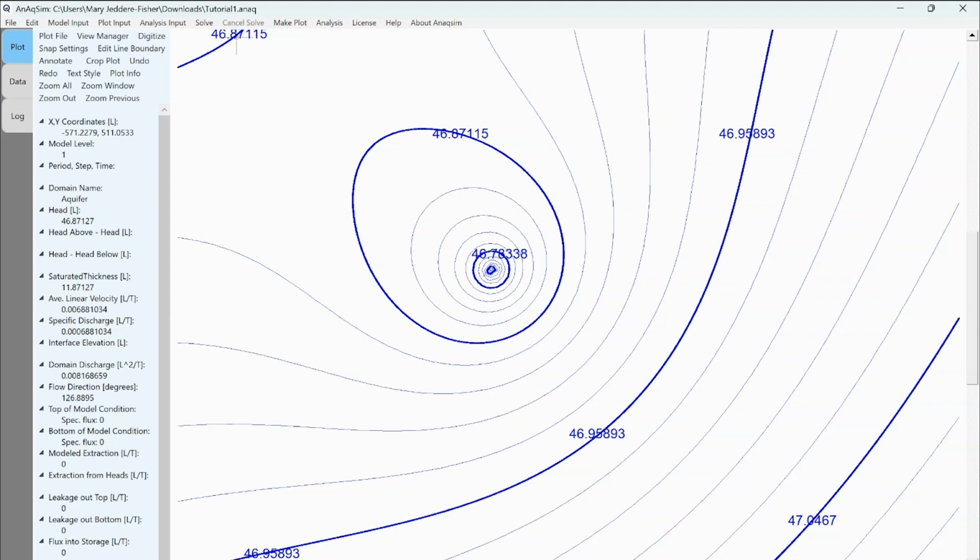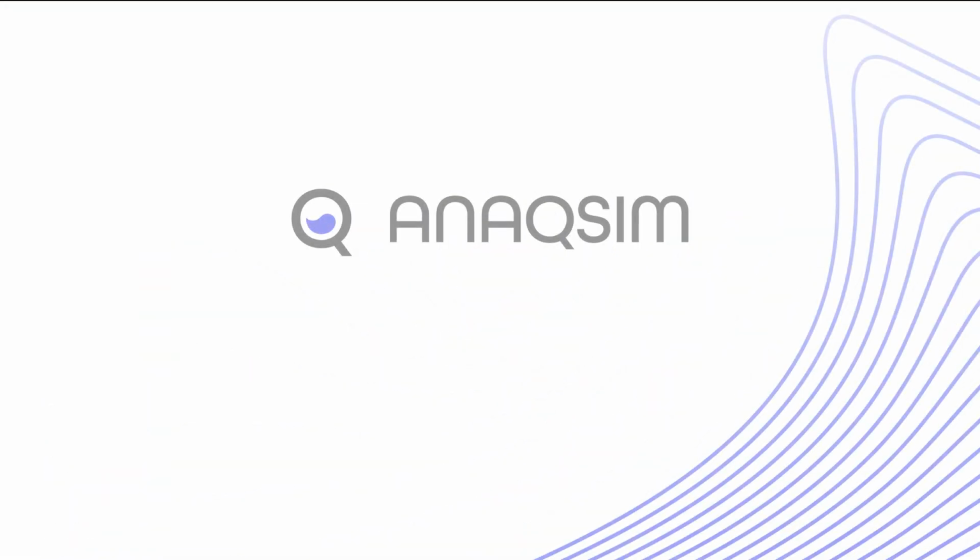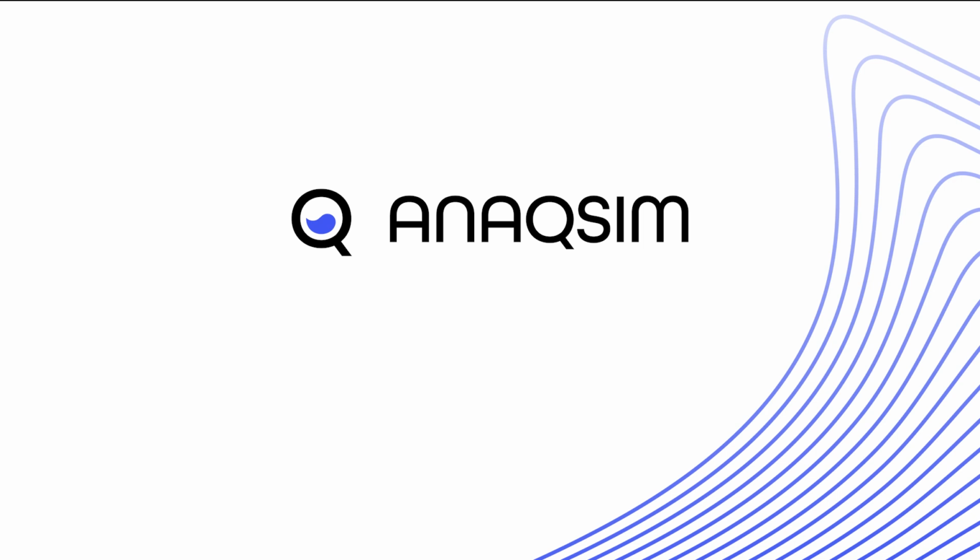And that's it. In just a few minutes, we built a functional groundwater model. Now it's your turn to experiment with your model. Remember, because Anaqsim doesn't use a mesh, you can tweak almost anything in your simulation with just a few clicks. Go ahead, try it out. Change the radius of the model, adjust the aquifer thickness, modify aquifer properties, move the well, or even add more wells. Just one important note, don't change the name of your aquifer domain. That will break the references in your model.